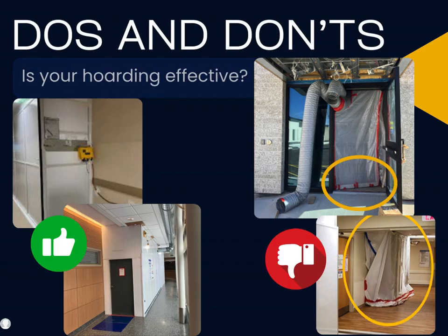The do's and don'ts of CRM. Is your hoarding effective? In the first set of pictures, the hoarding has a thick barrier that is properly sealed. In contrast, the second set of pictures shows plastic that is not fully sealed, allowing dust to escape from the job site and making it ineffective for adequate dust control.